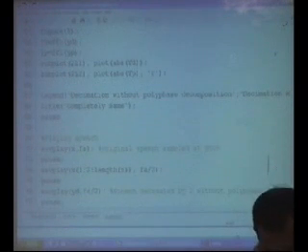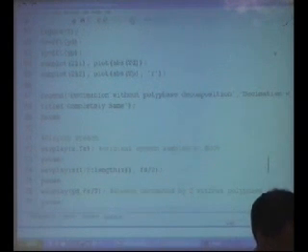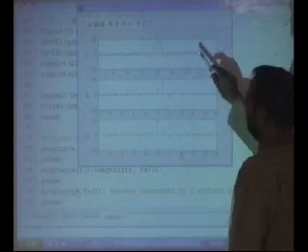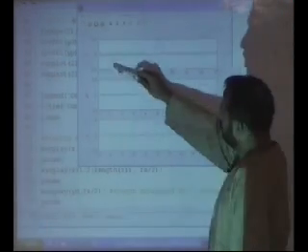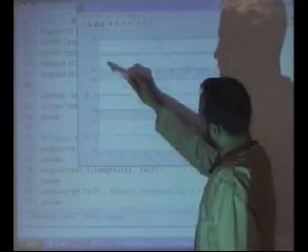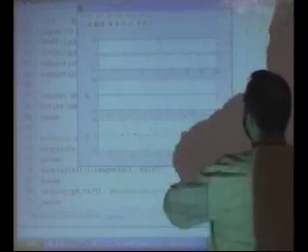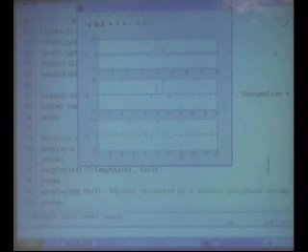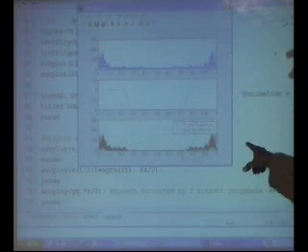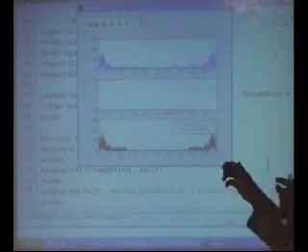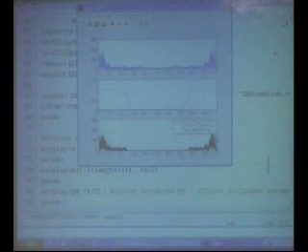And here, let me run this code. This is the original filter, and it is split into two filters. The first sample goes to this one, the second to this one, third, fourth, fifth, sixth. So out of these 40 samples, 20 go to this one and 20 go to the other. This is the polyphase decomposition. You design a filter for decimation, and you do this, and then do the same for the input samples. Once you apply the filter, you clean up the spectrum, and now you can do the decimation, and that decimation is achieved without throwing away samples.